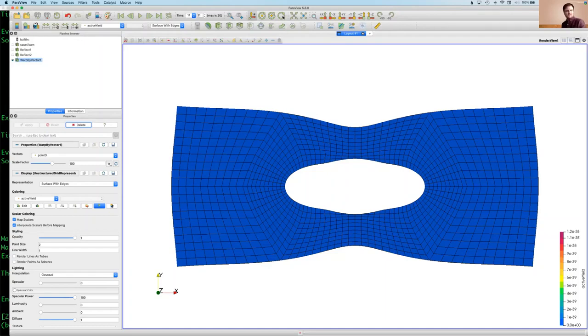However, timescales are often a challenge. The speed of sound in gases is often much lower than it is in solids. The speed of sound in solids could be an order of magnitude higher, so you have to be careful. Your time step may be limited by the Courant number in the solid, which is probably not what you want in your blast simulations. So maybe an implicit solid method actually is not a bad idea. I'm happy to chat further afterwards if you have particular cases you wanted to discuss.